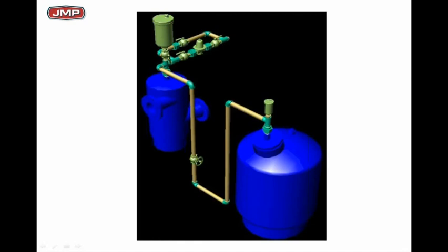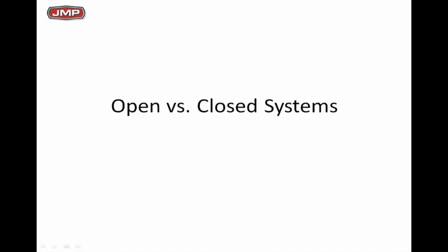In addition to that, you will see a bladder tank. And a bladder tank, as you may note in this particular slide, is at the same level as a Rolairtrol and not above it. It's at the same level. That's one of the advantages of an air removal system, as we'll talk about as we go. So we're going to go through each of these components today, talk about what they do, how they work, and how they're critical to making sure you have a good, modern, high-efficient system working for you.